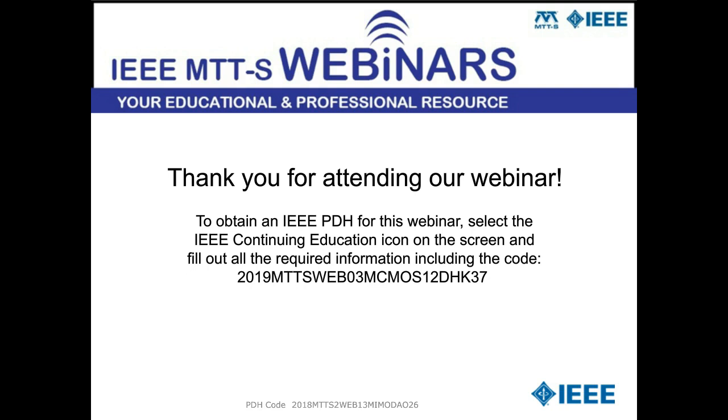So we typically have a divider that divides the frequency down by 2, which helps generate the 90-degree phase shift. And then we have buffering and so forth to get good square waves that eventually drive the switches in the circulator. And again, because it's CMOS and because we can put a lot of digital logic on the chip, we have circuitry to even calibrate the phase shift in case the phase shift isn't perfectly 90 degrees, and we can adjust it to get very precise phase shifts that minimize the loss and maximize the isolation.